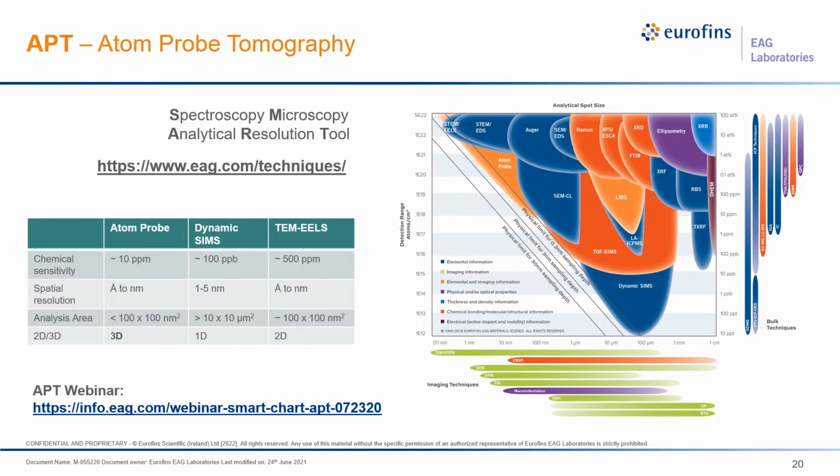And so from there, I'm going to talk a little bit about atom probe tomography and the benefits of having greater sensitivity for more dilute constituents, while also being able to look at the structure of the sample in a very localized way. For atom probe, you can see it sits up here in the upper left-hand corner of the chart. We've got pretty good detection limits down to about 1E18 for specific elements, and ultimately the resolution gets down into the nanometer scale.